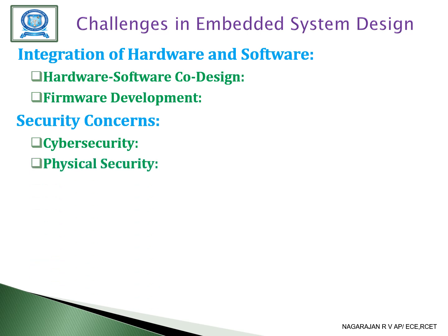Physical security. So these are the security concerns. Embedded systems deployed in the field such as in IoT devices or industrial controllers may be vulnerable to physical tampering. Designers may incorporate tamper-evident seals, secure enclosures, and hardware-based security modules to protect the system from physical attacks.